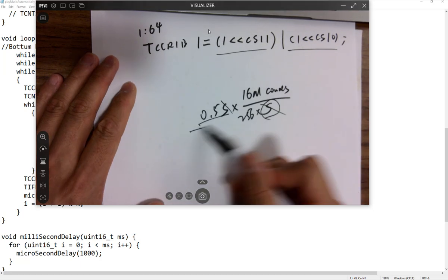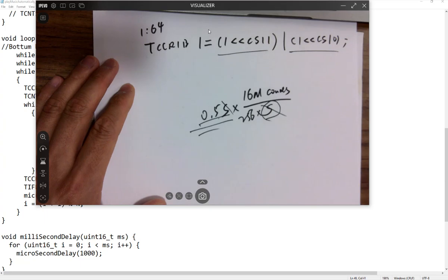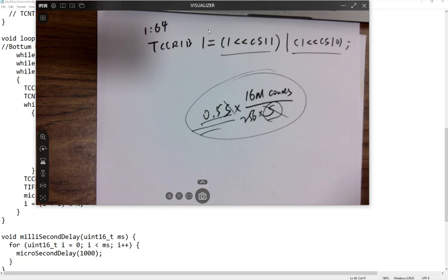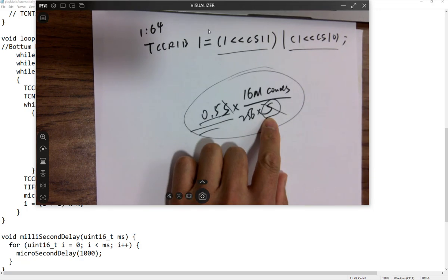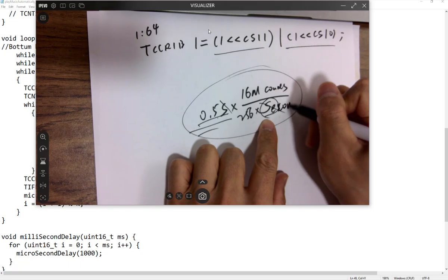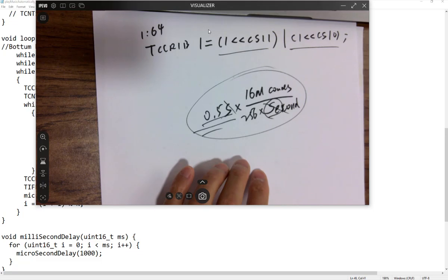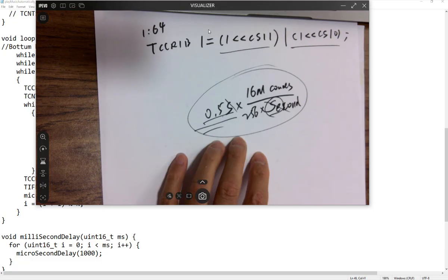If I have a different amount of time, you just replace this number with a different one, whatever on the paper, and then find out the counts you want to use or to be loaded in there. So question number 2, make sure that you're using the 256 as a prescaler instead of 1. Number 3, check if the LS, what's that? Oh, why is there the 5 in the bottom? Oh, that's seconds, not 5. Second. Oh, I'm sorry. Okay. Counts per second. Any other questions?